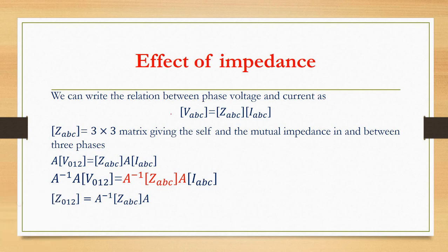And what is VABC? VABC is the unbalanced voltage, and in the previous video I have explained the relation between unbalanced voltage and the sequence components of the voltage. I have given the link in the description box. Okay, now I am going to write VABC. How can we equate VABC with V0, 1, 2? 0 means zero sequence component, 1 is the positive sequence component and 2 is the negative sequence component.